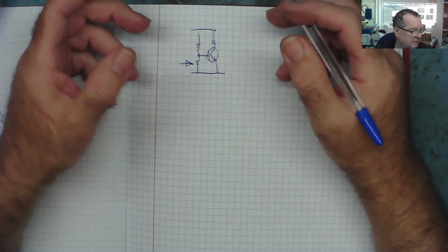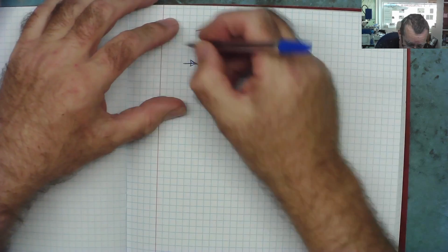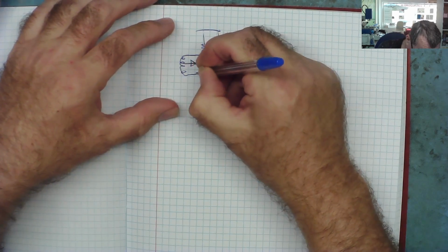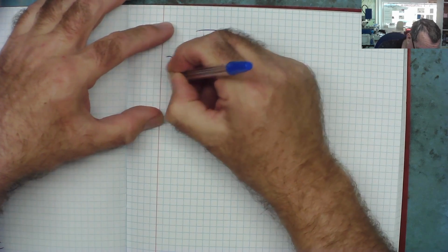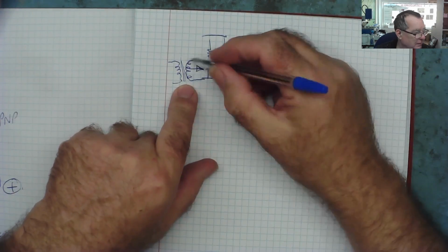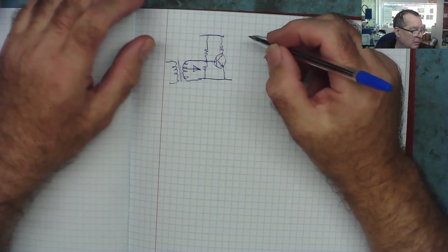So if you take the transistor out and it's actually okay, you see it's some low value resistor. And occasionally you'll find a similar circuit, but there's a coil here, an inductor coil, maybe even a transformer, this sort of thing. And again, this coil can read practically short to your multimeter. So sometimes that will let you down.